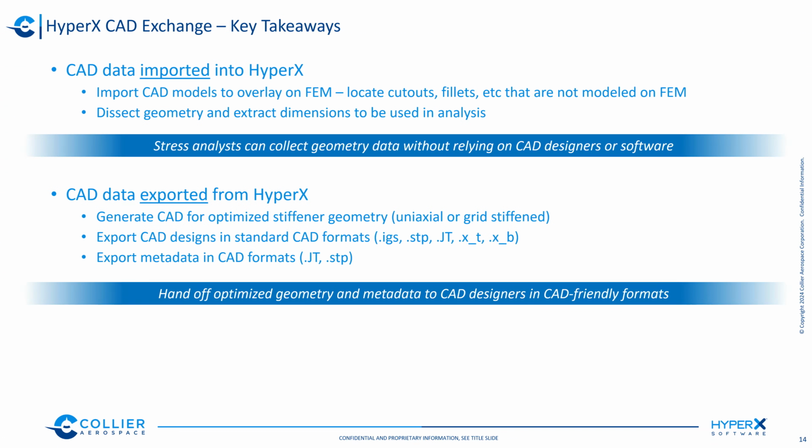So key takeaways: I showed the CAD data imported into HyperX, the goal being to import and overlay that geometry on the FEM to locate design details that we don't see in our FEM, and then extract geometry and other information to be used in analysis, all with the goal of enabling stress analysis to collect that geometry data without relying on external CAD designers or software.